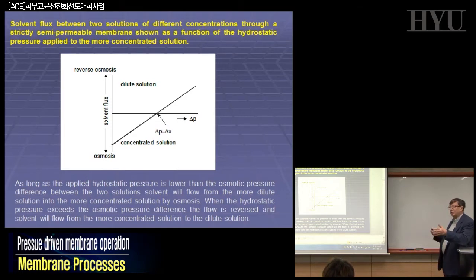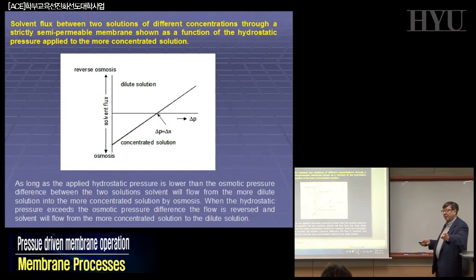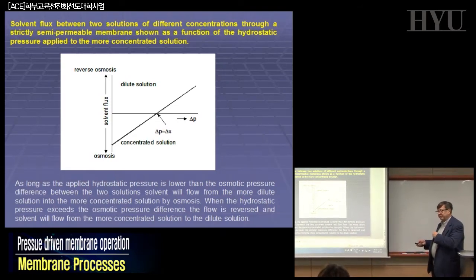Because if during your process, for any reason, and this reason is called concentration polarization phenomena, this problem exists, it's very real. If you don't control concentration polarization, your membrane, still ideal, still very good, does not extract water, but you are just working on the other side of your plot, in this negative side where water is entering the sea.